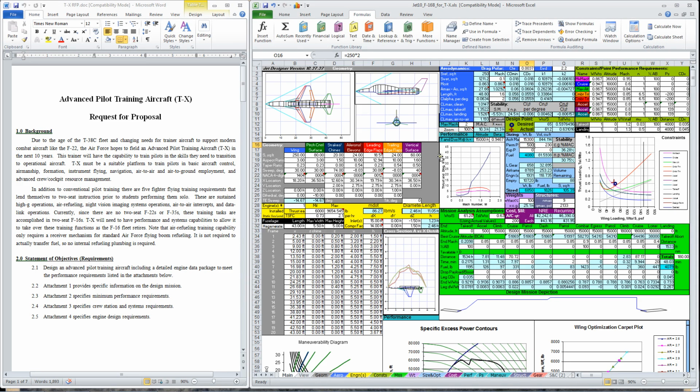And chances are we could have a smaller engine than we are. Let's try 5,500. All right, we once again have a positive solution to the sizing equation, and we have a slightly unstable airplane because we reduced the wing sweep. Maybe that's okay for maneuvering. Let's go ahead and fix it for now. Let's try 19 feet. Yeah, very slightly stable, probably better.